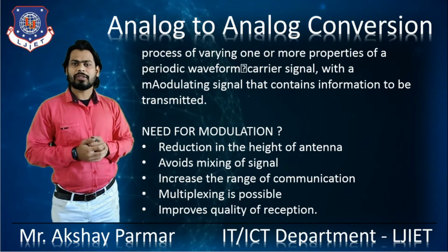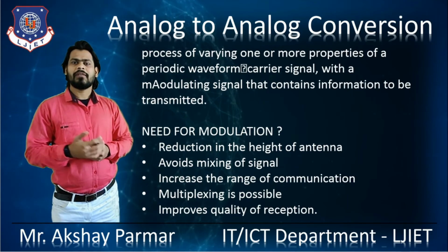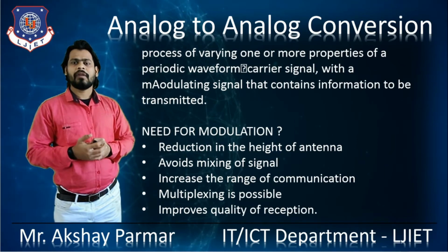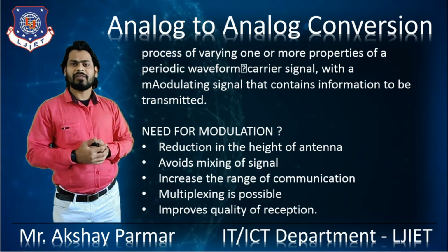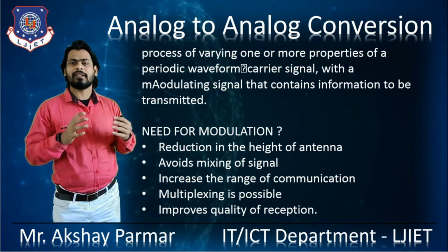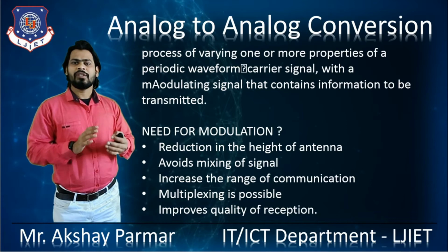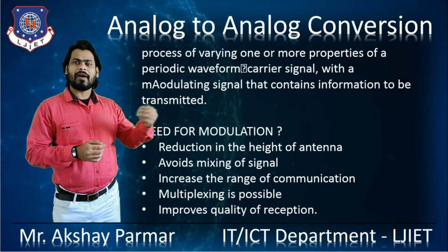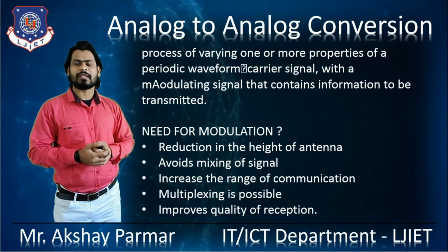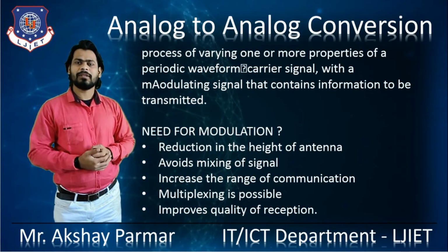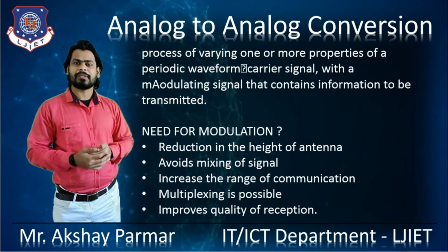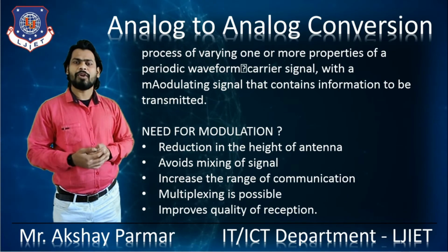Why do we need modulation? With the help of modulation, we can achieve a reduction in the height of the antenna. We avoid the mixing of signals and increase the range of communication. Yes, of course, it increases the range of communication. You can send the signal from a long distance with the help of this modulation technique. Multiplexing is possible with modulation, and it improves the quality of reception, right? So that's why we are using modulation.